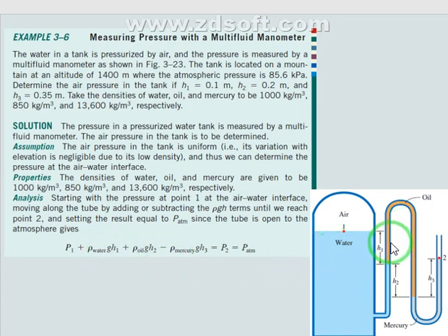That's number one. Then I look again, I see the next liquid is mercury. What is the level between oil and mercury? It's here. So it's a drop, meaning that the level between mercury and oil is lower than the starting level of the oil, meaning that I'm gonna use positive rho oil g h2.